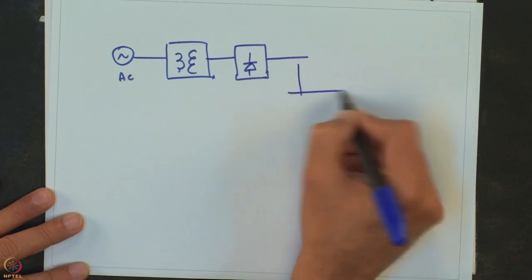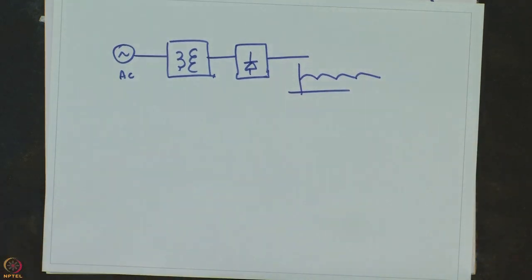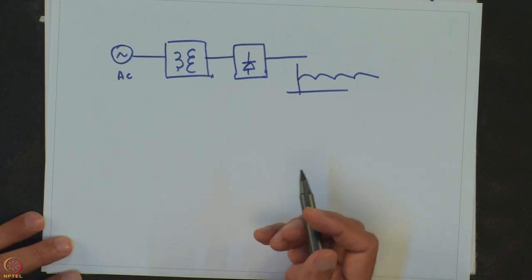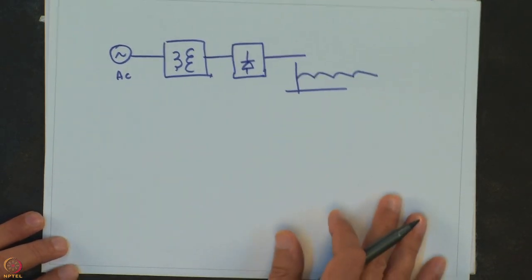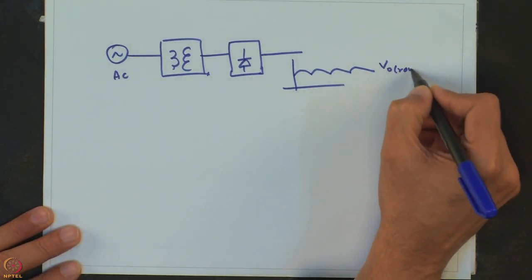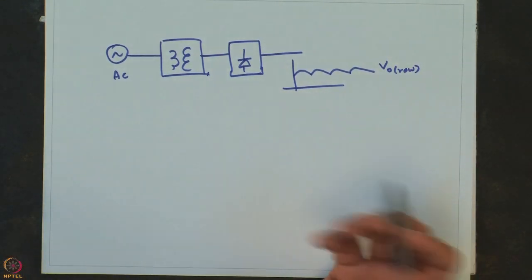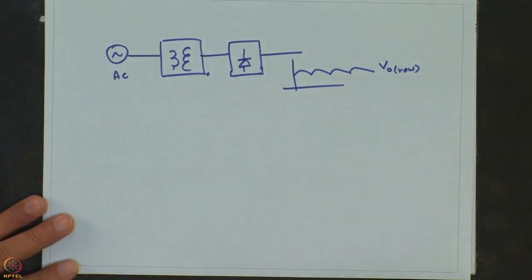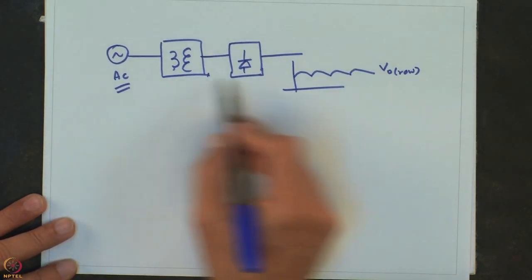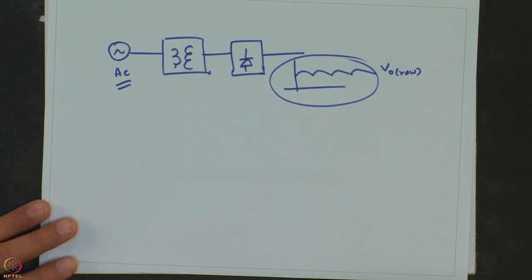So, basically if you recall, we got a voltage with some ripple, and we said that this ripple could be minimized by putting appropriate values of the filter components like capacitors and inductors. Now, the question is that this is still what you see here, I will just call it a raw voltage, because it is not regulated, not only because it has a lot of ripple, but also because if the AC voltage varies, there is no mechanism that this system will automatically keep itself at a constant value of voltage.